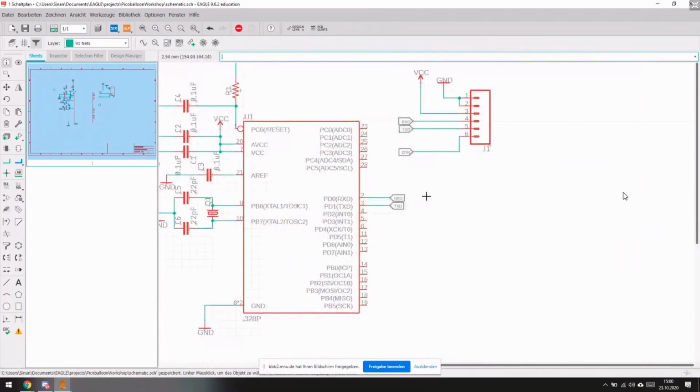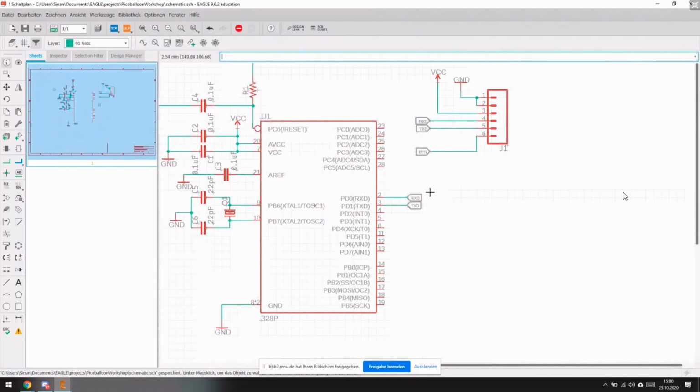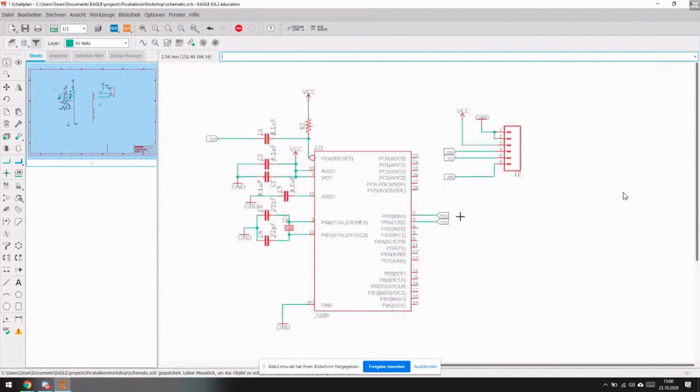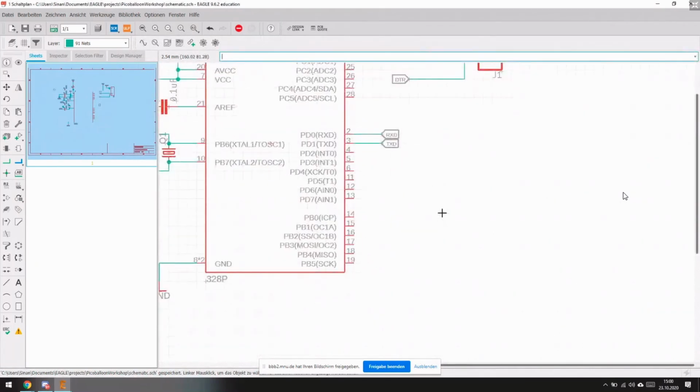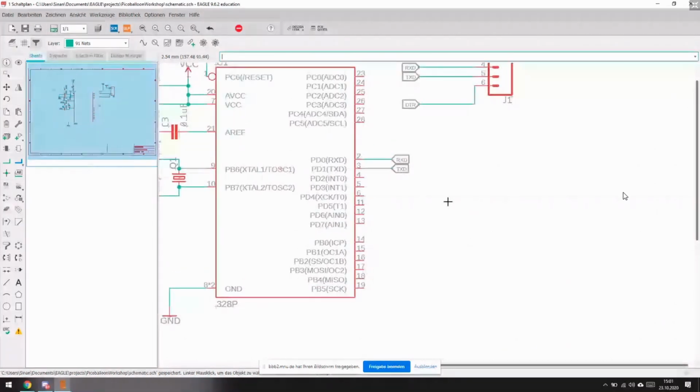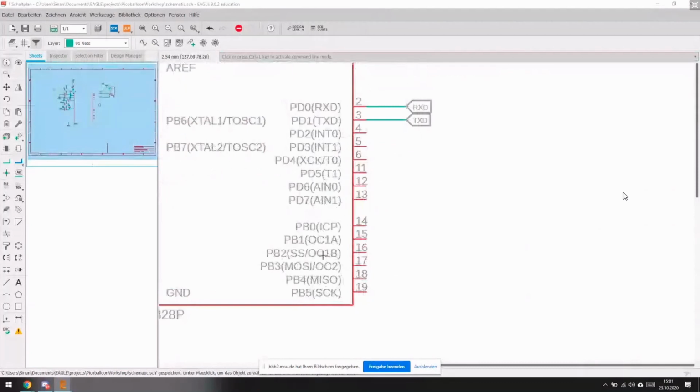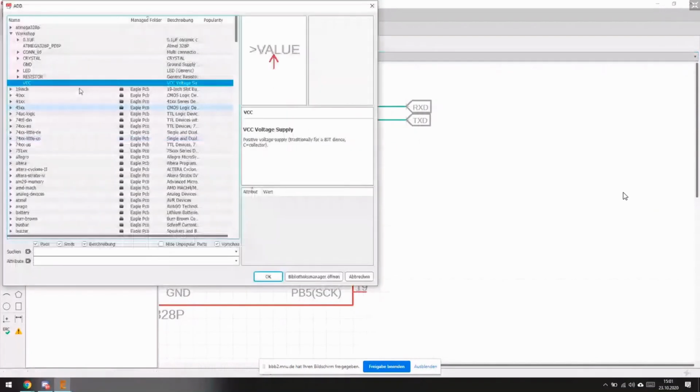But our board is pretty boring right now. It doesn't do anything. So we will add peripherals. Peripherals stands for almost anything, like adding sensors, LEDs, input-output devices, a keyboard, stuff like that. We will connect an LED to the pin PB1.